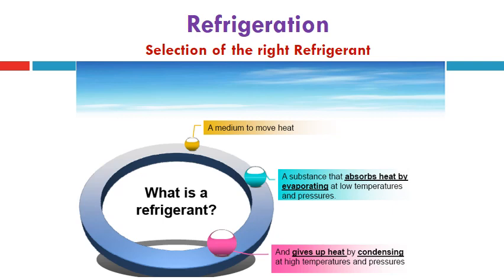Some problems will compare air cooling and water cooling for a certain type of refrigerant, to study the effect of the cooling media in transferring heat from the selected refrigerant of this vapor compression cycle, also taking into consideration the initial cost of the additional system components required in water-cooled systems, such as cooling water pumps, cooling water pipes, valves and fittings, and finally the cooling towers.